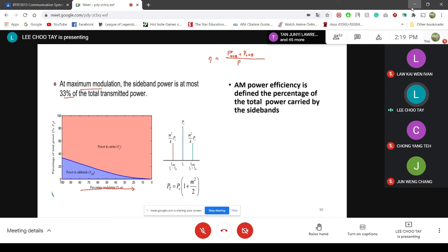And let's move on to the third method. Okay, before we move on to the third method, let's talk about the second method first. What's the weakness of the second method? The main weakness is in the phase shifter. In practice, it's not easy to get a phase shifter that gives you exactly 90-degree phase shift.